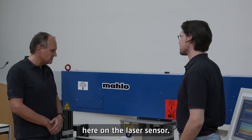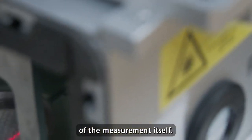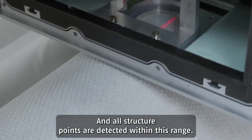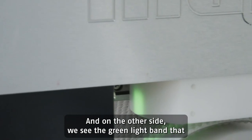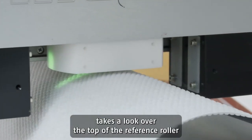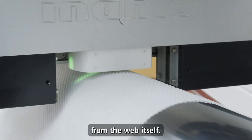Here on the laser sensor we see the red line, and this is the width of the measurement itself, and all structure points are detected within this range. And on the other side we see the green light band that takes a look over the top of the reference roller, and it detects the width of the shadow that comes from the web itself.